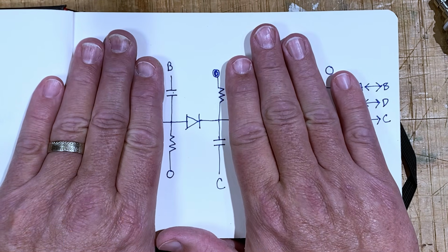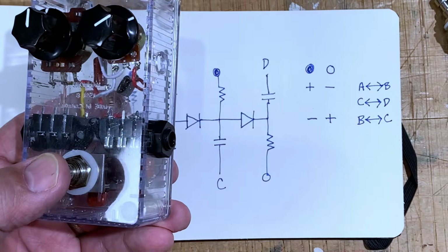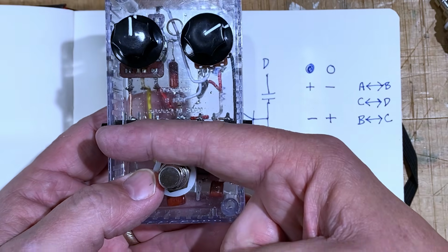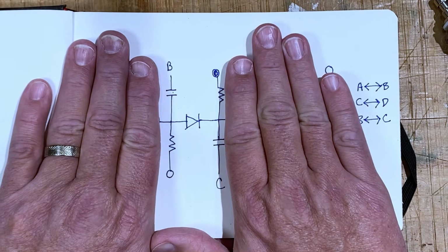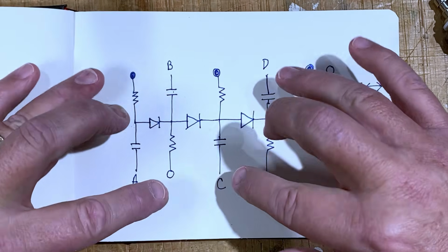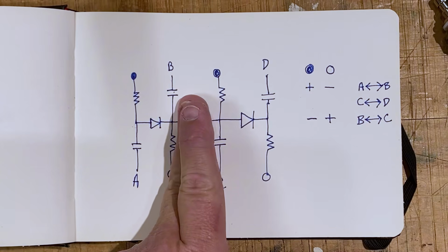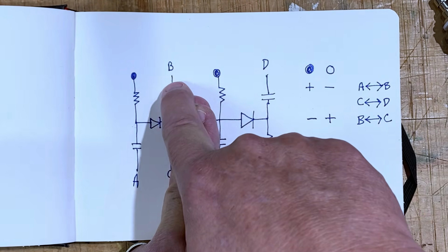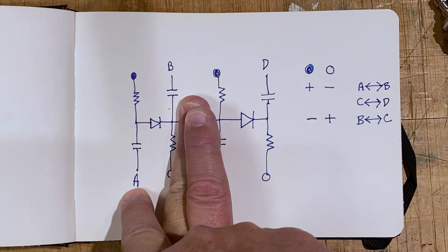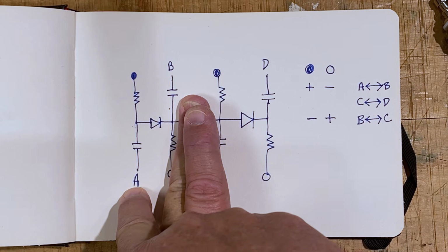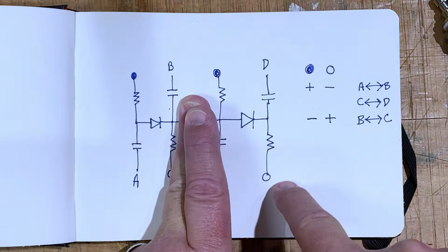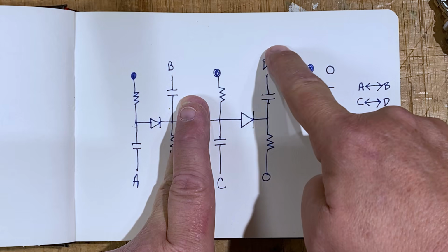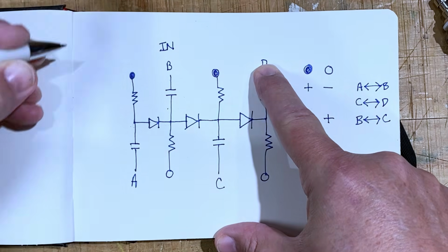So in my true bypass state, where the signal comes in and passes straight through to the output, I would want to use that center configuration. If I switch the voltages, this center path is blocked, and so now I can come in through this B input. This becomes my effects input, so the signal gets affected and comes on around. This will be my output, and this would be my effects output. That's my input.